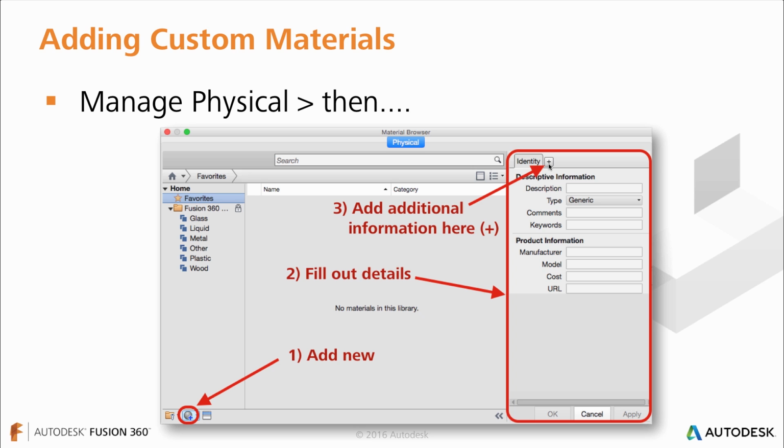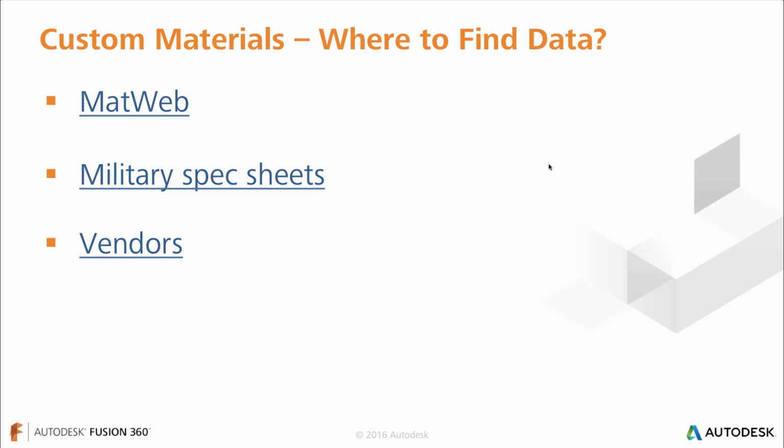When you add that, it adds other physical parameters to the material, things like your elastic modulus, things like the density, things that play into the actual calculations that you're doing. If it was a thermal problem, you'd have to consider conduction and specific heat and things like that. So click that plus sign. It'll give you the ability to add those additional details.